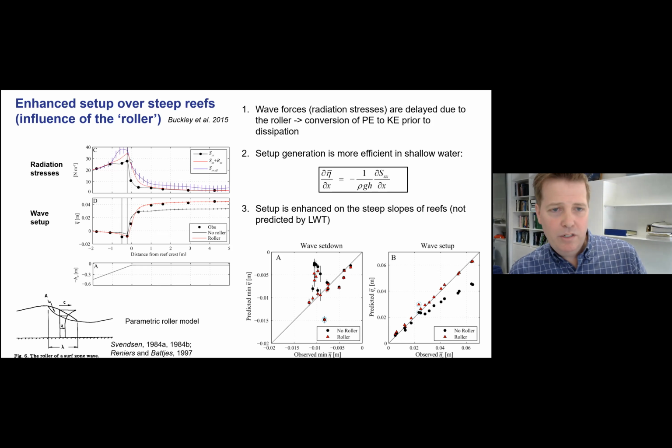And it essentially pushes the radiation stress gradients shoreward. One of the things we show is that for the same value of a radiation stress gradient, if that occurs in shallower water when H is smaller, we get a larger setup response.